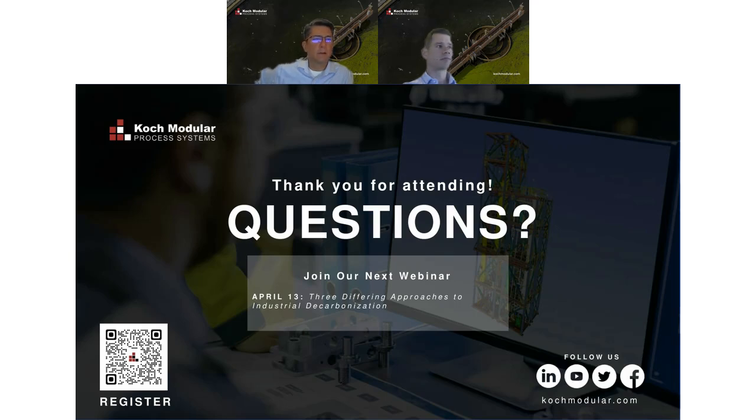Okay, great, thank you. Another question is, can you define the term flooding inside the column? So for example, what is that physical phenomenon that's happening when flooding is occurring? Sure. So flooding occurs essentially when you're pushing the column too hard in terms of flow rates or agitation speed. And essentially what you see is that the dispersed phase begins to build up within the column, and left unchecked, eventually you have both phases going out both ends of the column.